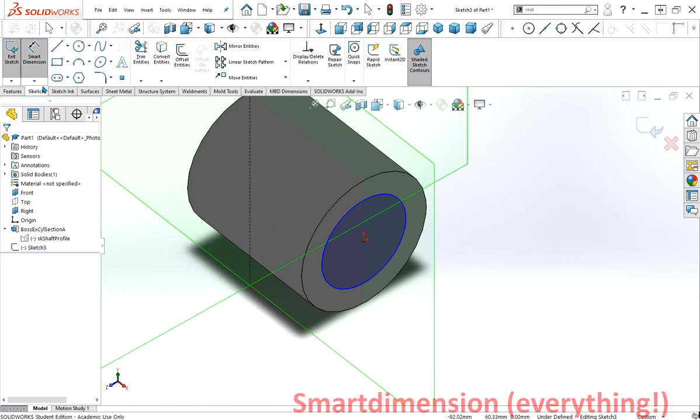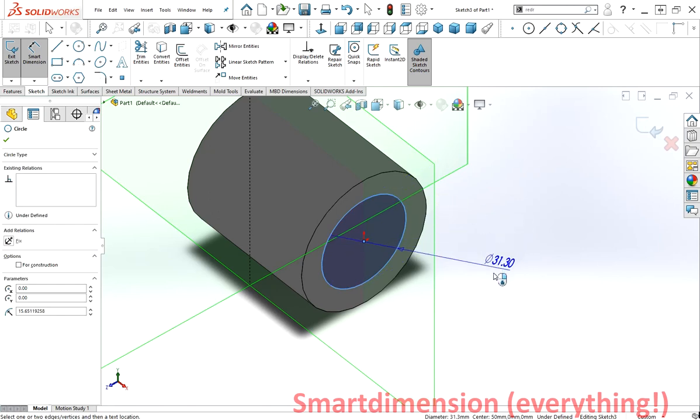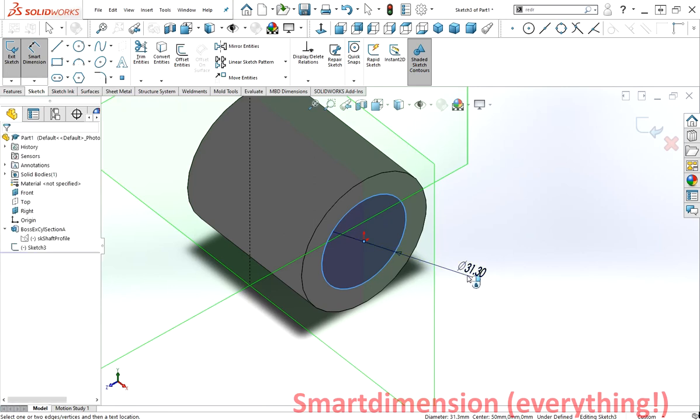Click the button there. If you smart dimension something, all you need to do is click the circumference of the circle, and if you move around, it will give you different types of dimension. It doesn't really matter at this stage which type, because you could sort all that out in the drawing, but I would suggest these are the clearest.